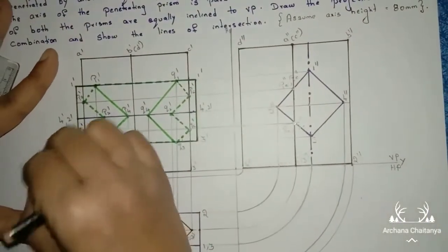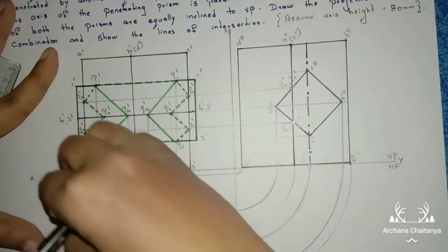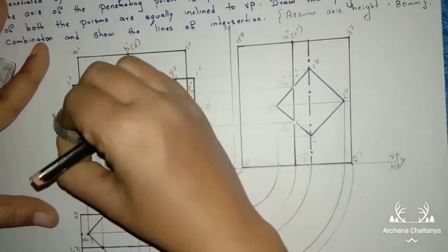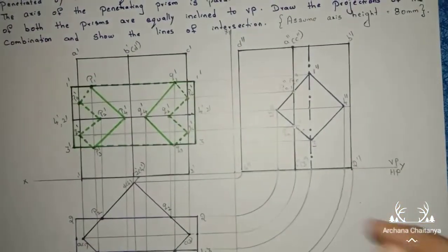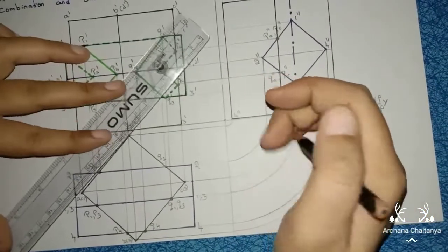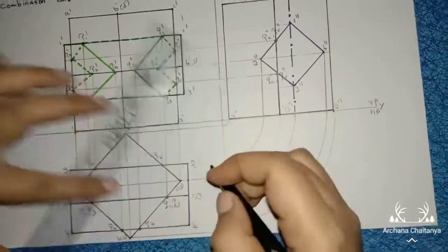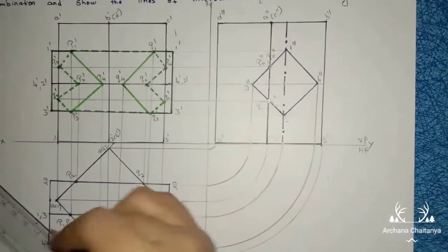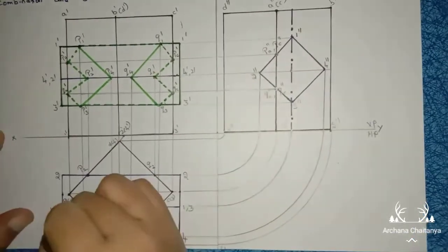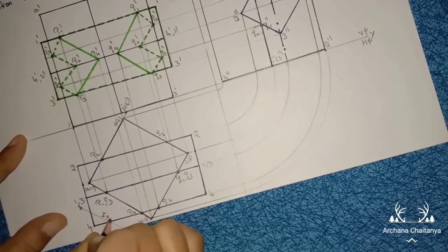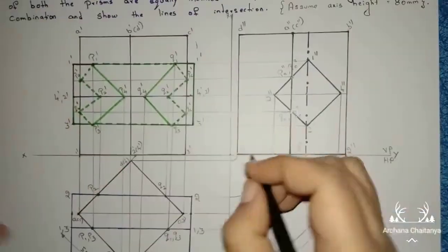Okay, we will mark here only. You should not mark the dimensions in the diagram, so just extend this outside here. I am not having place, just extend this outside and write down here length of this square is here 50 mm. Draw the dimensional line properly and write down here this is 50 mm.